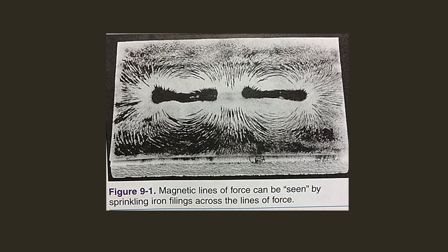Each magnetic line of force travels from the north pole to the south pole through space. The line returns to the north pole through the magnet itself. These closed loops of the magnetic field can be described as magnetic circuits. Compare the magnetic circuit to the electrical circuit. The magnetizing force can be compared to voltage, and the magnetic lines of force can be compared to current.